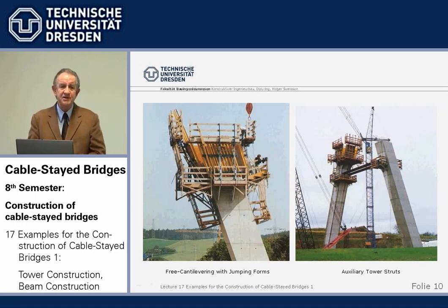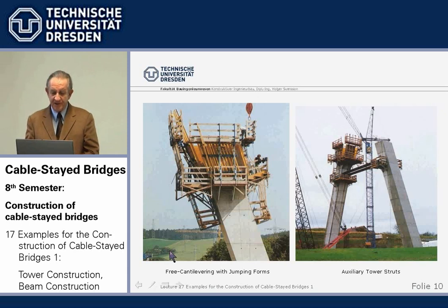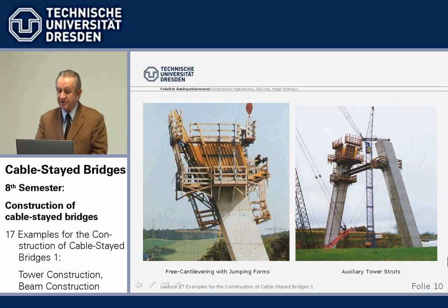So we as engineers should always prefer jumping forms, because there we have the time, also in adverse weather, to align the forms properly and to have the built-in items in place, without being under time pressure. So, free cantilevering preferably with jumping forms.